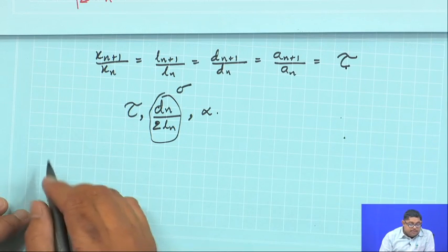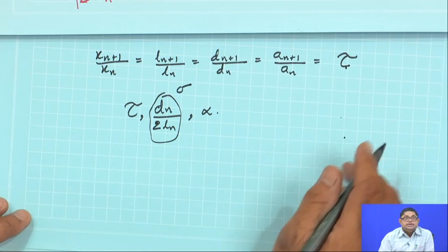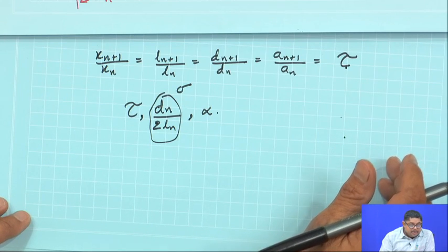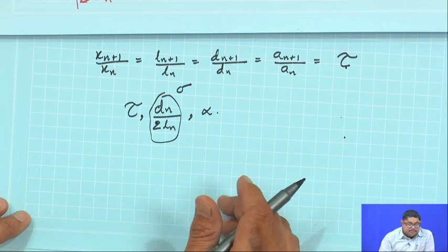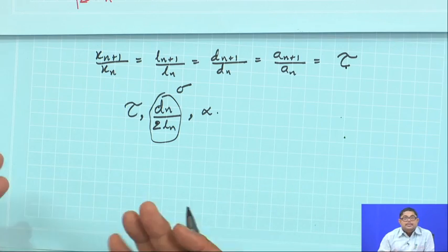So, if we multiply all dimensions of the array by tau, it scales itself with element n becoming element n plus 1. So, the array will have the same radiating properties at all frequencies that are related by a factor tau.